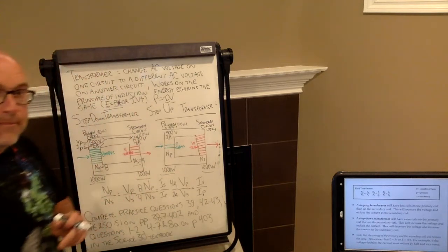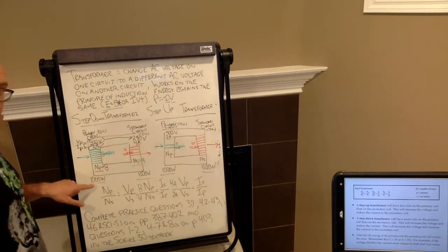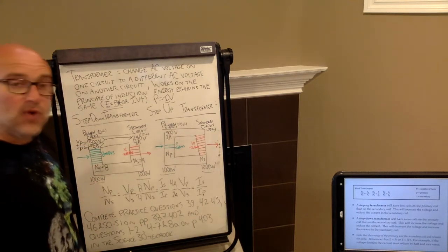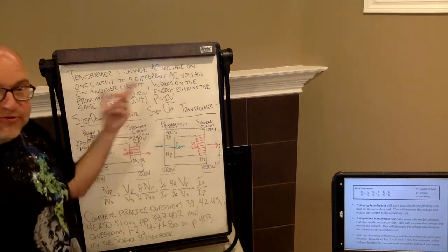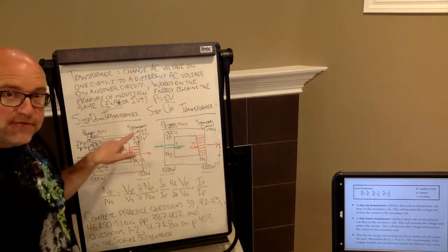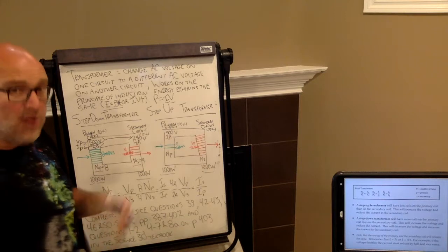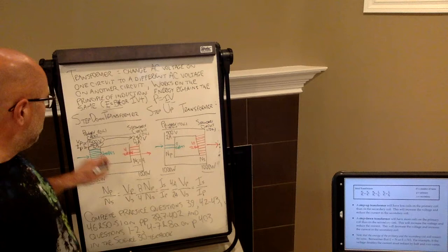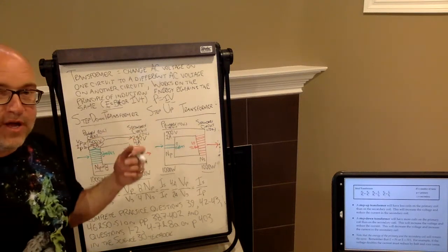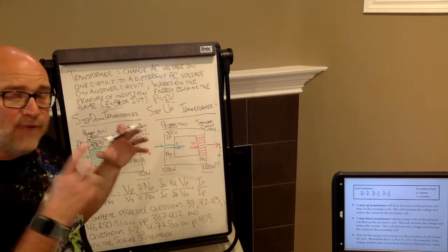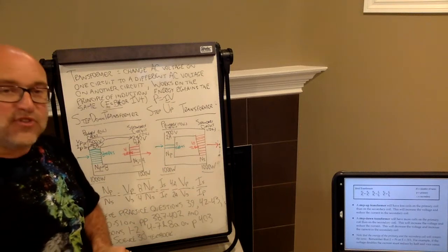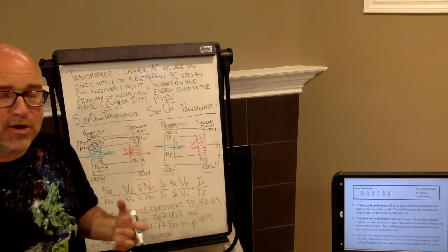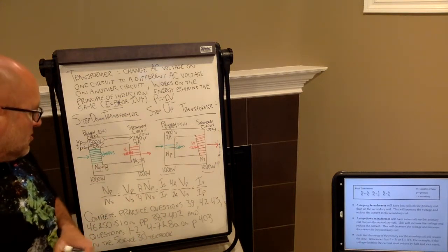Now let's confirm our numbers here. I said that we had 1,000 watts of power on the primary coil. 500 times 2, 5 times 200 is going to give me 1,000. I times V, right? What about my secondary coil? I got 250 volts times 4 amps, which is also going to be equal to 1,000 watts of power. There's the conversion. So this would be an example of a transformer in Morinville that's taking the high voltage coming into town, and we're stepping it down to a lower voltage. It's going to be safer for us to use in our houses and our homes. That would be the example of a step-down transformer.